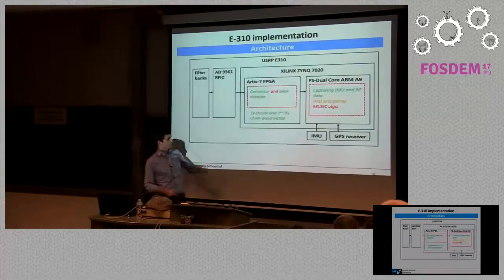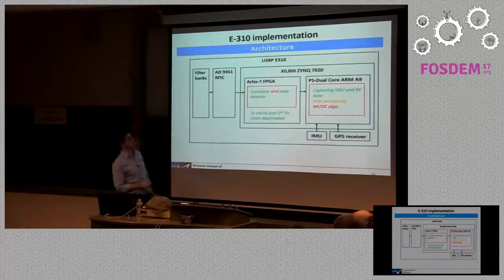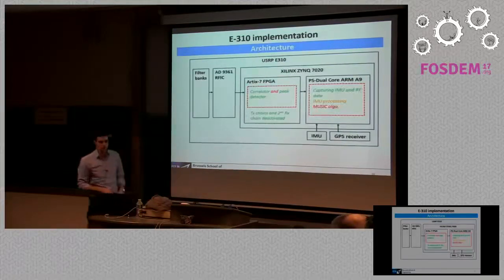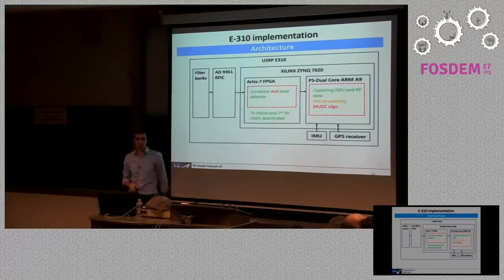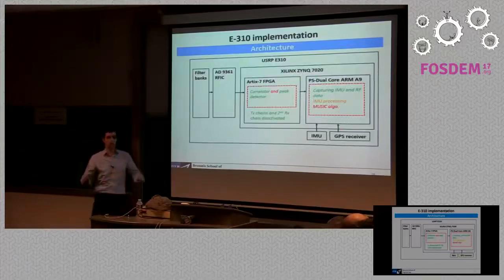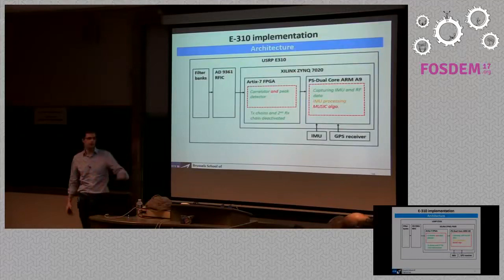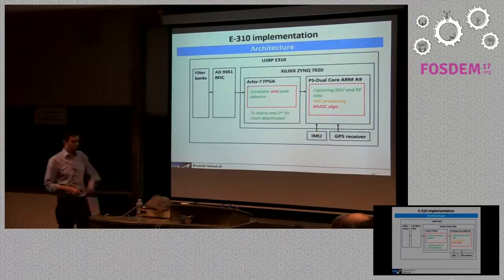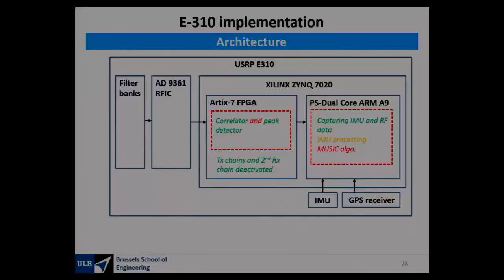So where do we stand? Well, the green parts are what has been done. The red part is what's missing here. So part of the processing is done in the FPGA again. This went through some work because I wasn't using RFNoC, so that's my fault. And it took some time to get up to speed with the USRP 3 generation of the FPGA. We have everything working when we use it in the simulator, even when we feed it with actual measured USRP signals. But when synthesizing the whole thing, I ran out of slices, so we have to find some way to optimize this or offload some of the processing.